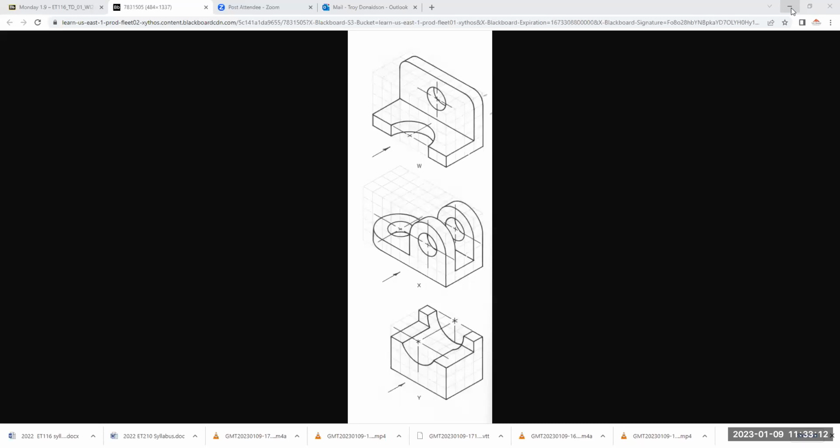All right. So I'm going to set it current because I want to use annotative. These are two different ones. We want annotative. Set current, close. So if I go here, it should say annotative, right? For the dimension style. So that's good. So now I have to figure out the scale. The way you do that is here in layout. So in paper space, when I zoom, the paper zooms, right? And I'm just zooming with the roller mouse.